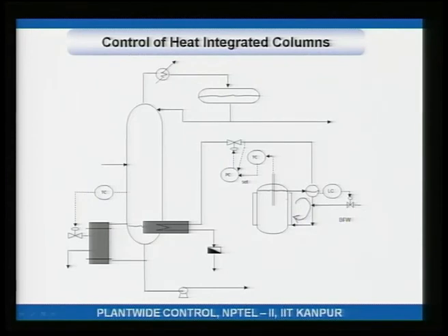Because heat gets transferred across the walls, the water that goes here flashes and generates steam. This is the steam that gets generated. Okay. So, this is of course boiler feed water. Now, because steam is getting generated, the level of the water here will go down, that is made up by putting in more boiler feed water, which is here. Okay. Now, this steam is being used to get some reboil in this distillation column.